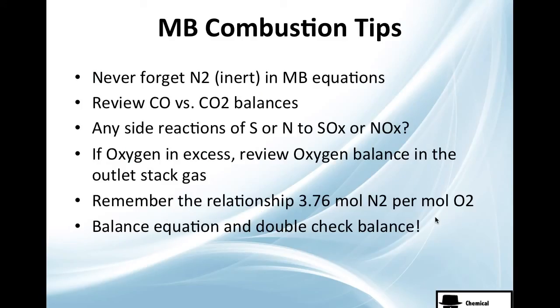Let me just show you the last tips for mass balancing combustion examples and problems. Please never ever forget nitrogen. Nitrogen is inert, I know, it doesn't react, but it will affect the composition. And when you see energy balances, you will see that you will need to heat the nitrogen. So please guys, take care.